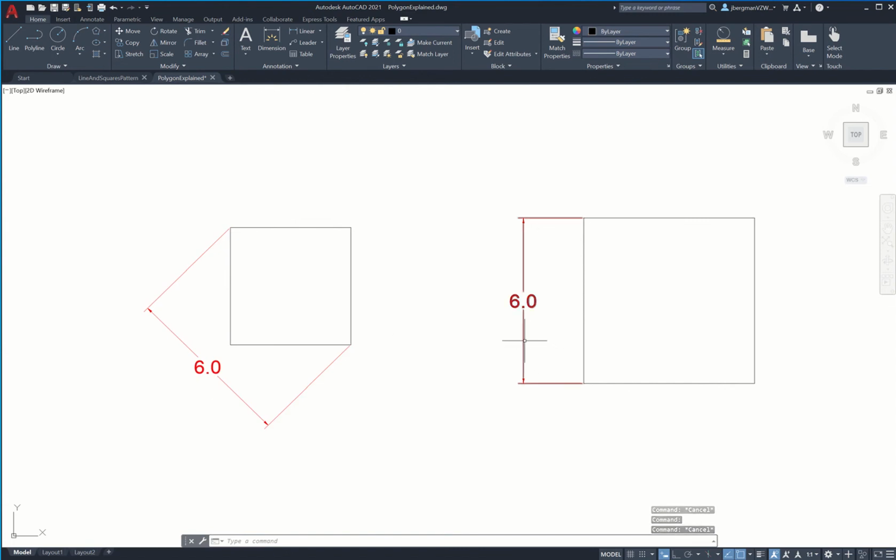And if you were given something that was dimensioned like this, we are going to use circumscribed, which just means if I were to draw a circle with a radius of 3, then this polygon would be outside of the circle. And in this one, it would be inside of the circle. Okay, so this is what the two different things look like: circumscribed, inscribed, with a circle of radius 3.